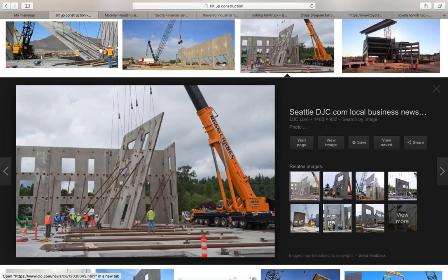Wear proof of fall protection, right? ANSI rated fall protection. Keeping the work area clean, right? Block piles of reinforcing steel to prevent sideways movement. So any type of steel that we have, look at page 7. A perfect example is all those pieces of rebar there. Let's say they're taller or higher. We don't want to roll it on an employee, right? So if they were bigger or taller, we may be blocking them, okay, to make sure they're prevented from falling back on us. Also, wearing goggles with the proper lenses